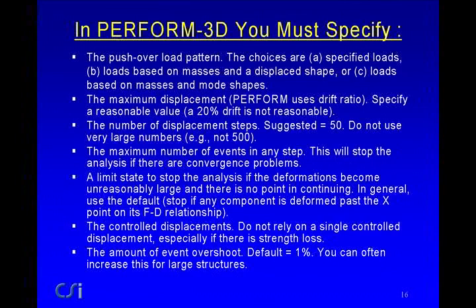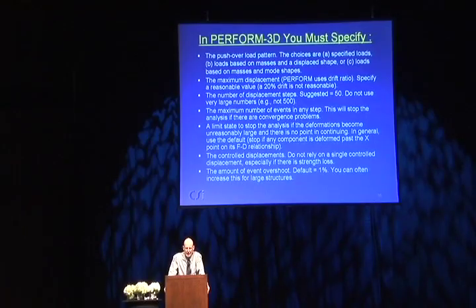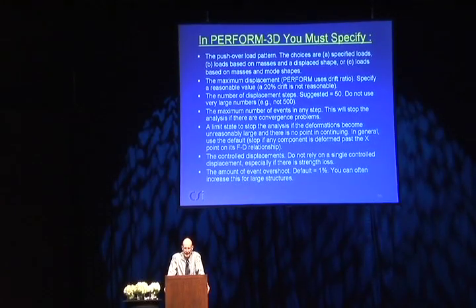So you do have to specify certain things in Perform 3D when you do a static pushover analysis. You don't have to know a lot about the analysis method, but you still have to specify a few things. Firstly, you have to specify the pushover load pattern, and you have a number of choices. You can use a specified load pattern. You can specify a displaced shape, and it will calculate the forces based on that displaced shape and the masses. For example, if you specify a linear displaced shape over the height of the building, this would correspond to a triangular load pattern, but based on the masses. The loads don't necessarily increase linearly.